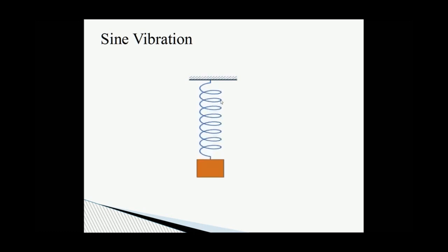Damping causes a structure or system to give up its vibration energy in the form of friction, or in other words, heat. So in the real world, a structure or a system will move and eventually the energy will decay as it is converted into heat through friction. Now let's go ahead and calculate the natural or resonant frequency of this spring mass system. We're not going to use any math, except for a very simple division problem.